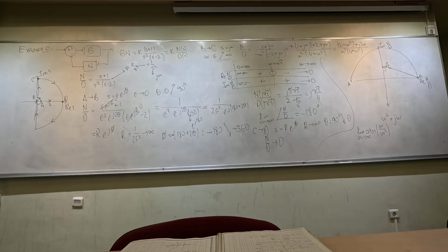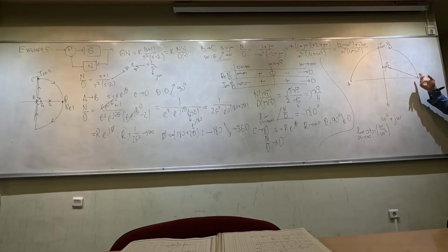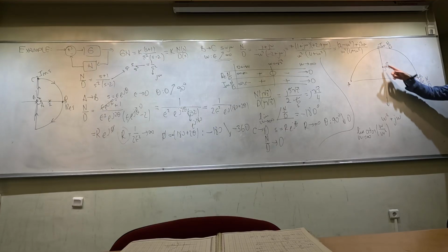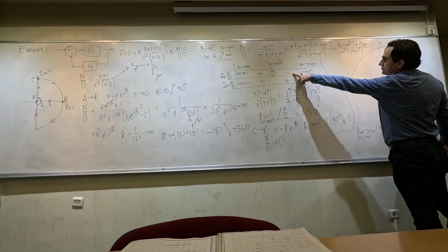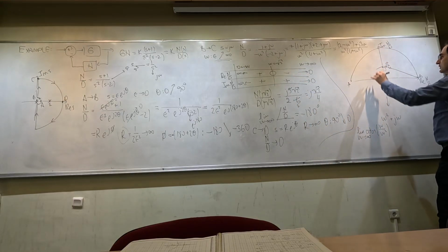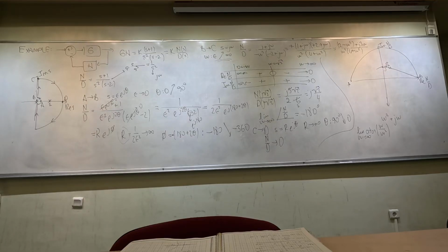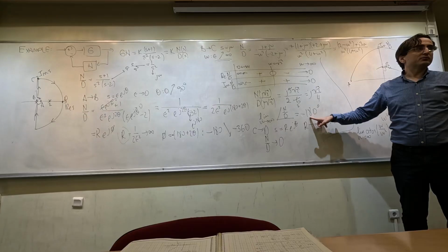Because at the end, we're going to be concentrating on the number of encirclements of some real axis points, it is really not important how you go there as long as you remain in this quadrant. And then I'm going to cross the quadrants. I will go to the quadrant where the real part is negative and the imaginary part is positive. Everything should converge to 0, but while converging to 0, I need to keep the angle at minus 180.